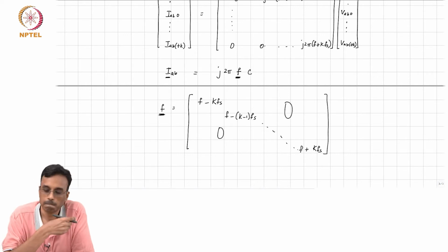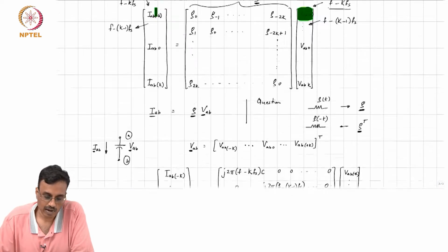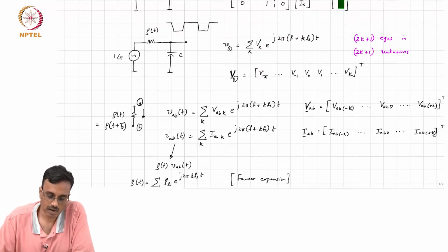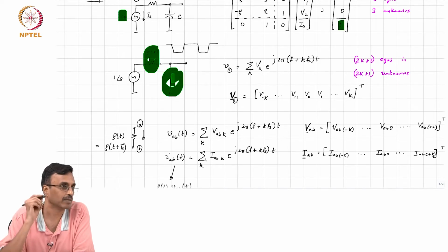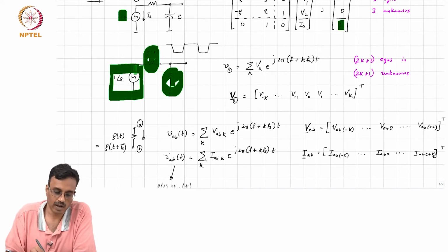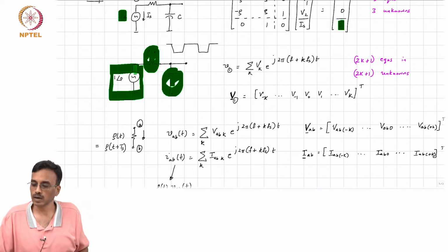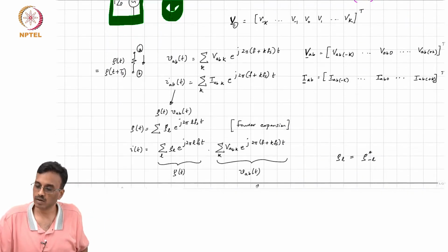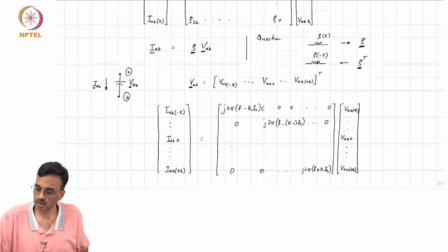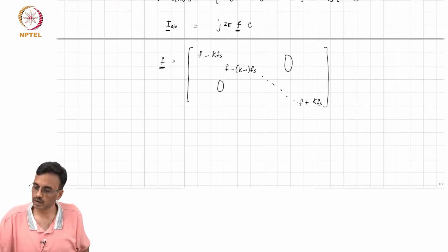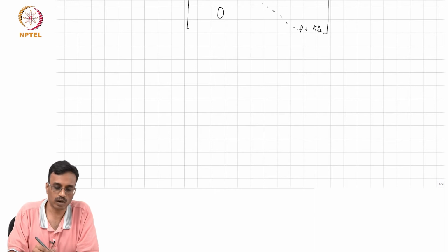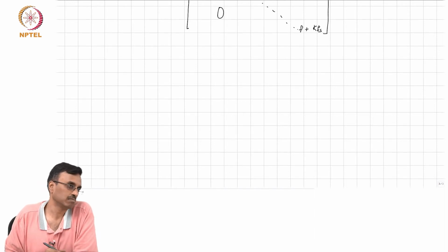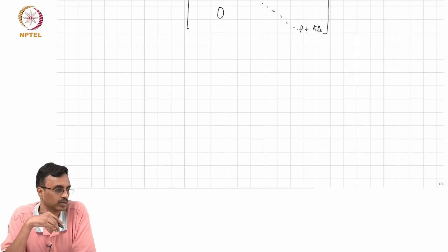All right. So, we have two elements here. We know the MNA stamp of this guy, we know the MNA stamp of that guy. The only thing remaining is this one. So, what do you suggest we do? Voltage source. As usual, what do we do? In a voltage source, the unknown is the current through the voltage source.